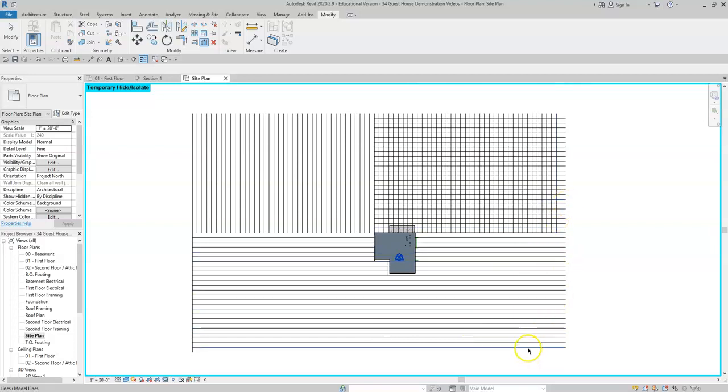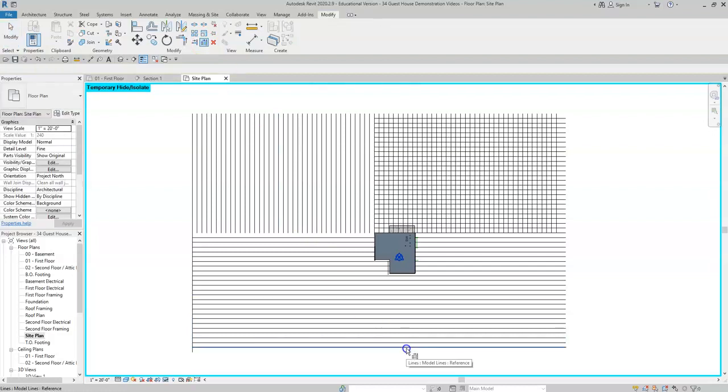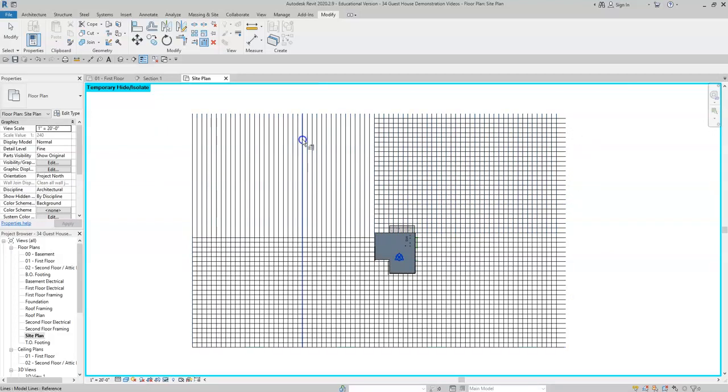Same thing for up here. I'm going to click this baseline. Click the multiple trim extend. Actually, you need to click the command first, and then click the model lines. The model line, and then my second click will be the highlight of all of these lines all the way across. So there's 1, and then there's 2. And there they are.